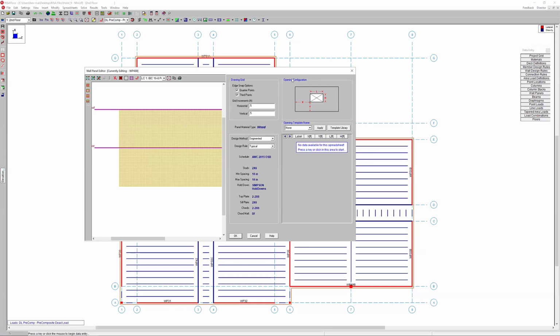The first here is the ability to create your openings in a spreadsheet, but we still have the ability to create an opening graphically. So let's start with that. If I add an opening here, I can just pick. The first thing you'll see that's different, that I really like when you're modeling, is that you no longer have to only look for the coordinate system that was down here in this location. You can see the coordinates jumping right on the screen, so it's much easier to input.